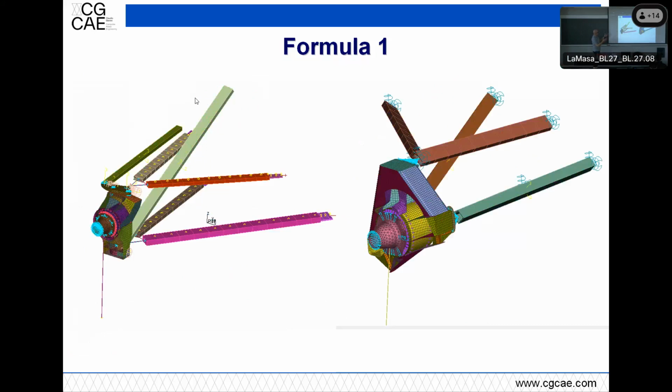So here, up to now, we talked about strength. The stress engineer needs to guarantee that the structures that are designed and then produced can resist the loads that are foreseen. In those cases, they were the ones provided by the FIA, so the regulations say you have to apply this load. Of course, the test is still there. They don't rely on calculations. It's you that iterate until you think you are confident, and then you go to the test. You produce the part and you go to the test.